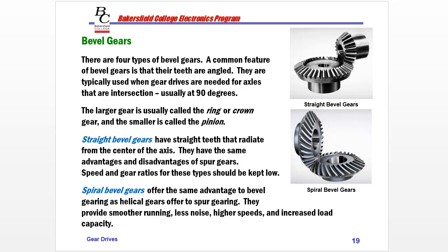The next type of gears are bevel gears. And remember when we looked at the differential? That's what this would look like. It would use what's called a hypoid bevel for a ring and pinion on a differential, and we'd have the pinion, which is going to be on the drive shaft, spinning the ring gear.